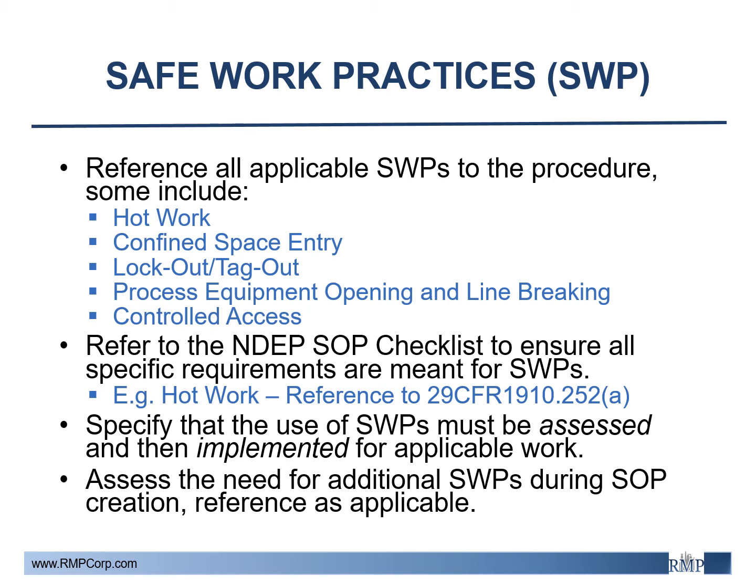Applicable safe work practices, or SWPs, should be referenced in the procedures to allow operators to utilize them as needed. Some common SWPs are listed in this slide. The NDEP SOP checklist also includes specific requirements met for some SWPs, such as hot work, which requires that fire prevention and protection requirements be implemented prior to work per 29 CFR. It should also be specified in the SOP that any work in the procedure should be assessed if not already identified and the applicable SWP be implemented. The need for additional SWPs should also be assessed while creating SOPs to ensure that all procedures are performed safely.